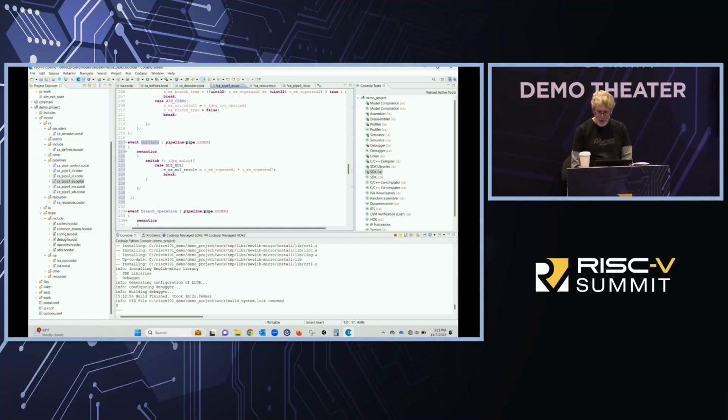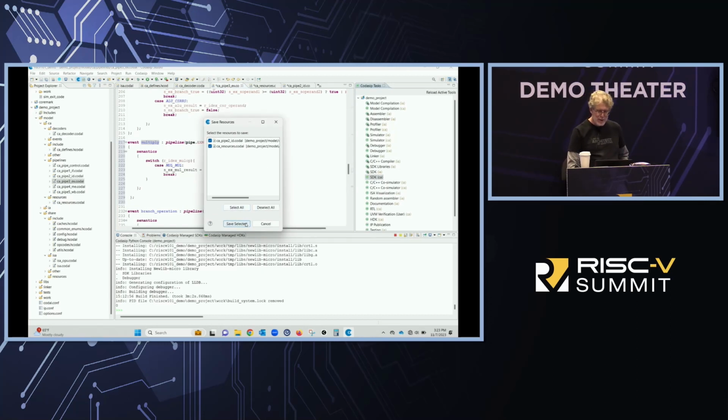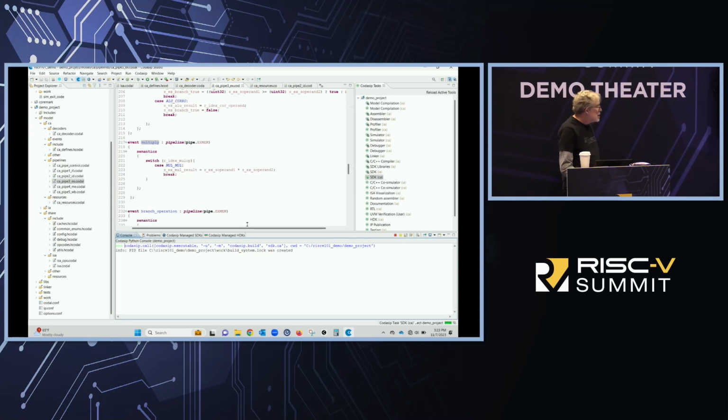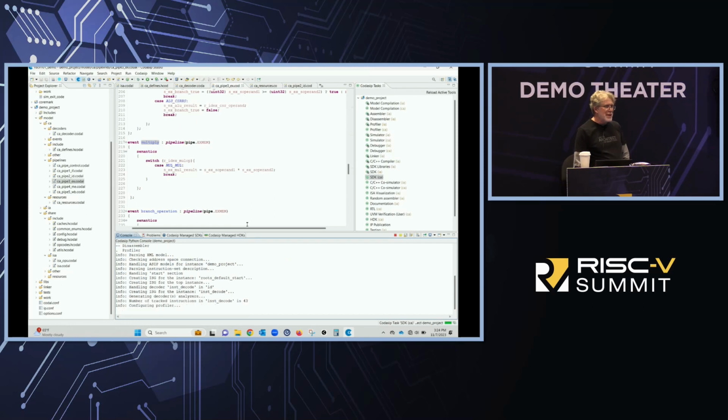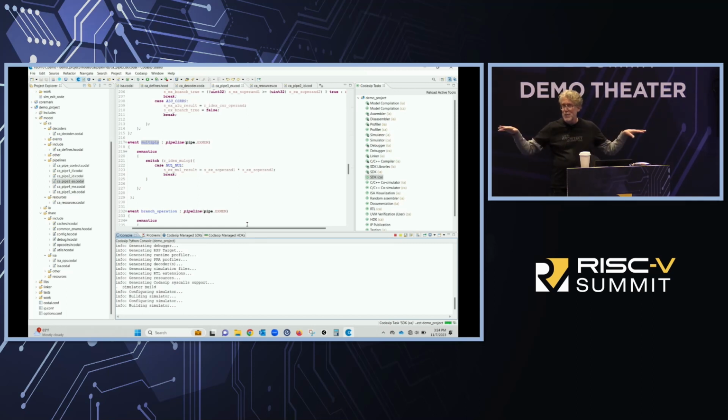Let's see it. I'm going to click on STK, so we'll build it. Were we at like 73 million instructions, something like that? I forgot how many million instructions. It was something like 73 million when I had no multiply. So we're going to run it again and see how many it takes now. It should be significantly less because my multiply, as I defined it here, is going to tell the RTL to generate a single, parallel multiplier. So we'll execute the multiply in one cycle.